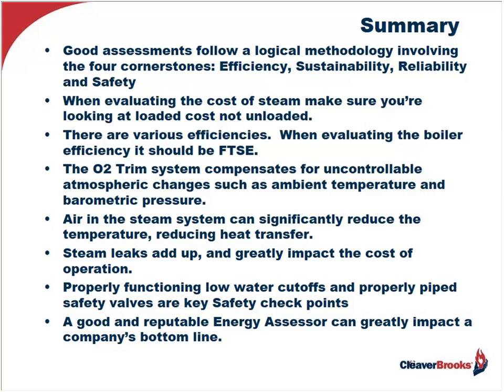The O2 trim system compensates for uncontrollable atmospheric changes such as ambient temperature and barometric pressure. It won't tune your burner. After it's been properly tuned, it will compensate. Air in the steam system can significantly reduce the temperature, reducing heat transfer, increasing fuel cost, possibly affecting the product. Steam leaks add up, as I showed you, and greatly impact the cost of operation.